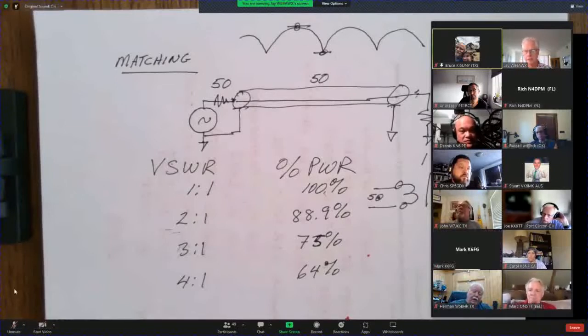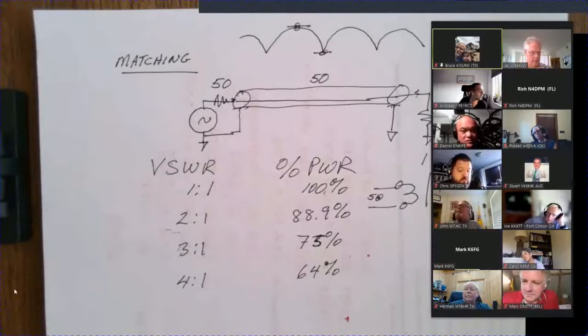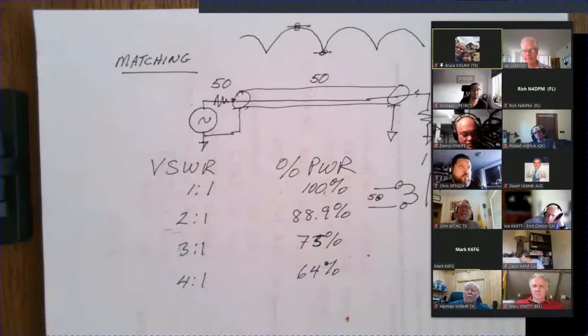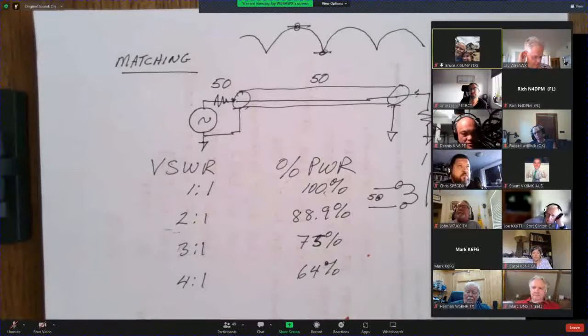I've had that experience, and what caused it in my situation was a less than perfect match at the antenna end of the coax, and the SWR varies along the length of the coax. With the Rig Expert, you have a given fixed length to the meter, whereas if you go directly into the transceiver, the length of connecting wire between its internal SWR bridge and the cable is different. And in fact, sometimes adding a little bit of coax in series with the existing coax line will give you a much different SWR reading on the internal SWR bridge.